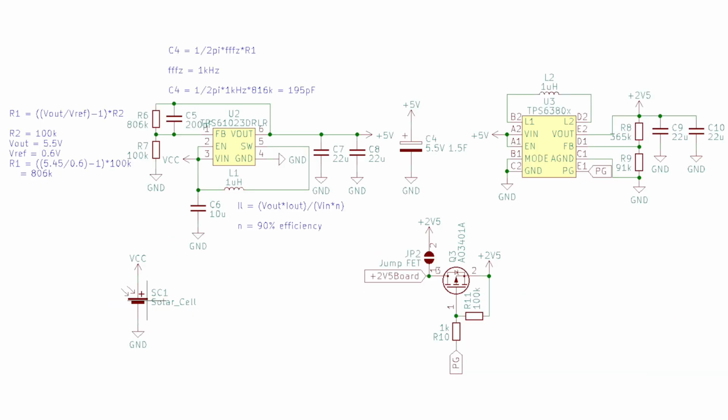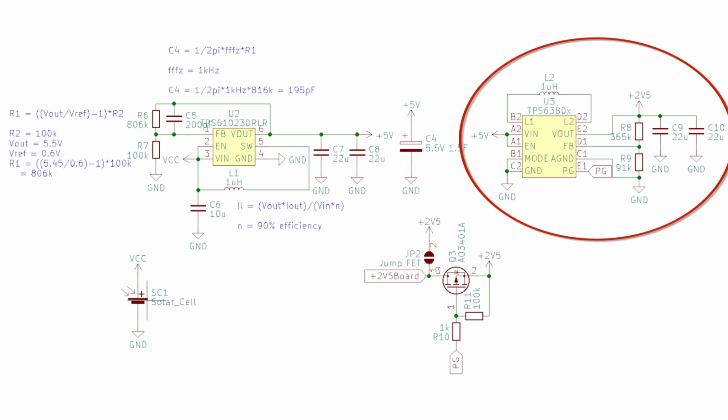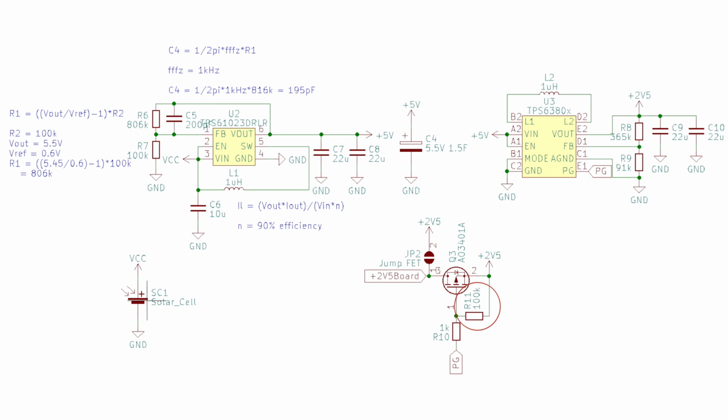Now, did I expect that result? In theory, the first boost converter should use 30 microamps and the second one 11 microamps. Also, the pull-up of the MOSFET should use another 25 microamps. This totals 66 microamps. So I assume that 29 microamps must be lost during conversion, as well as by the supercap self-discharging, which seems about right to me. I did try to replace all the pull-up resistors with 1 megaohm ones, but this did not change the energy consumption at all, which I did not expect and cannot explain.